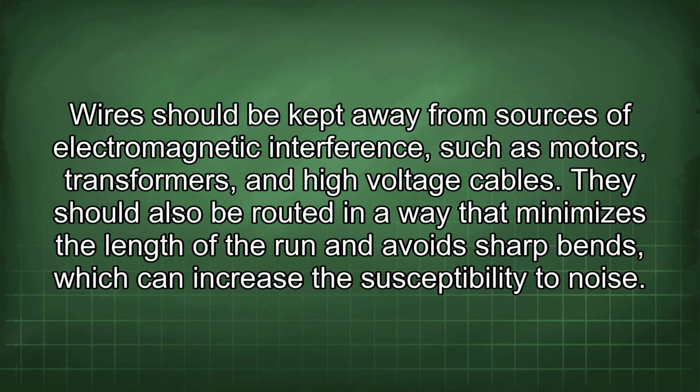Wires should be kept away from sources of electromagnetic interference, such as motors, transformers, and high-voltage cables. They should also be routed in a way that minimizes the length of the run and avoids sharp bends, which can increase the susceptibility to noise.